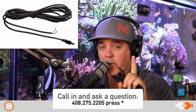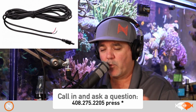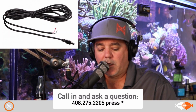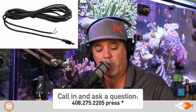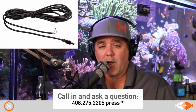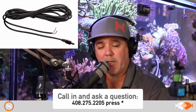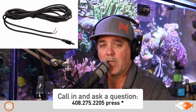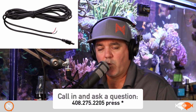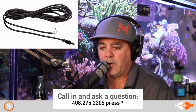You can do a lot of different things, but the one thing to be sure of is that it's not a high current device. What do I mean by that? It should be around 30 watts or less, okay? It's very important to note also that the total amount of everything that you have between the One Links and these DC24s should not exceed 100 watts while they are on. If all of the things could be on and at 100% at the same time and it equaled more than 100 watts, that would be bad, okay? So just keep that in mind when you're deciding what you're going to plug in. Any one of those DC24 ports, I believe they're rated to 35. Call it safe, call it 30, and you should be good.